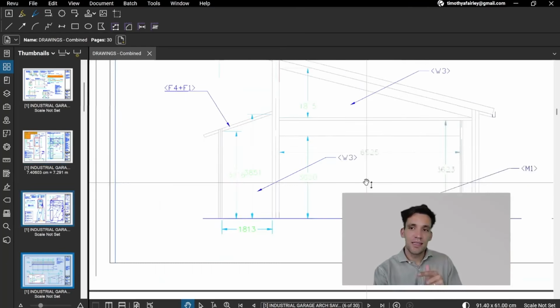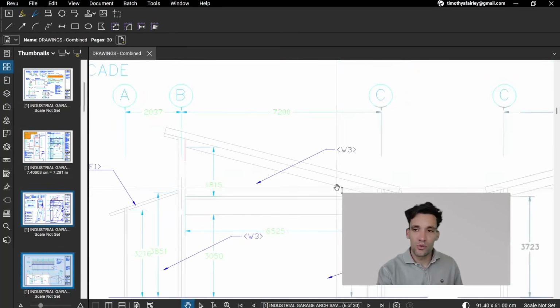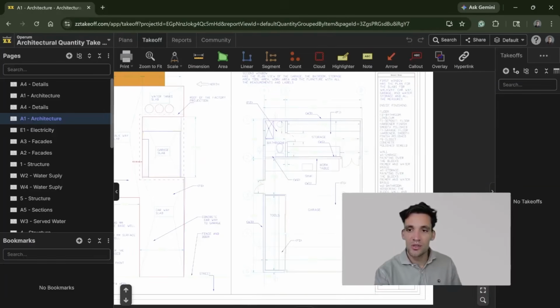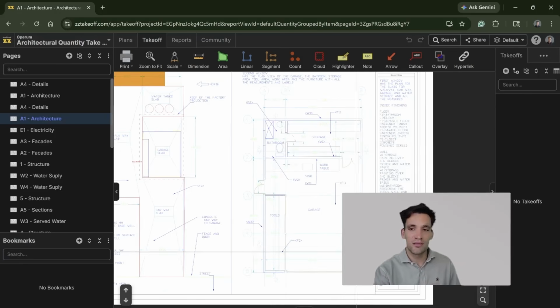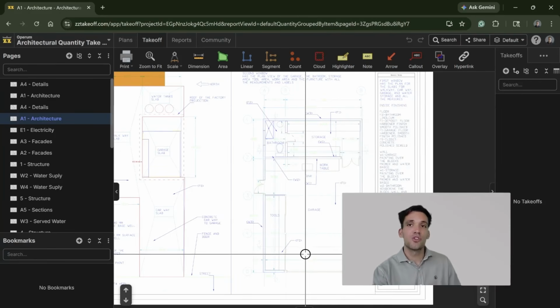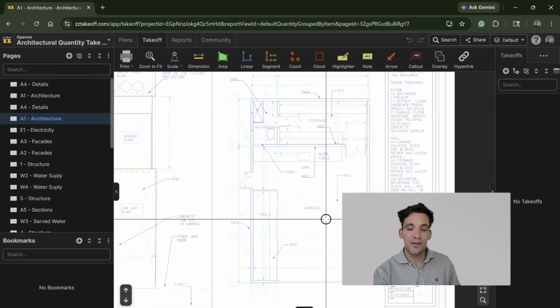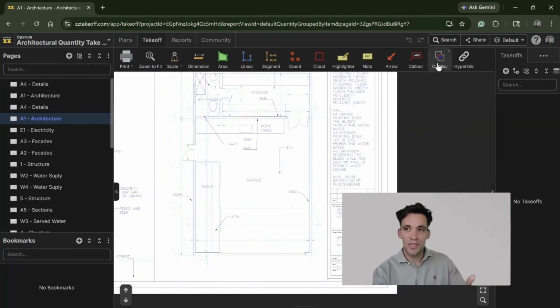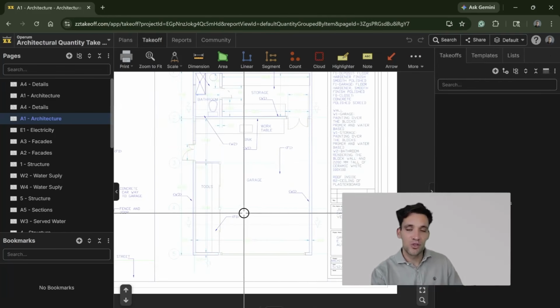So what I'm looking at in the drawings, I'm looking at these drawings through Bluebeam, but I find Bluebeam isn't great for quantity takeoff. So I use ZZ Takeoff for the actual takeoff and building out the library of assemblies. But really, you can use PlanSwift, whatever. There's a lot of tools that do very similar things. The concept is really all the same, that you have some primary quantity you measure from the drawing and then a library of assemblies or secondary quantities that you derive from this.